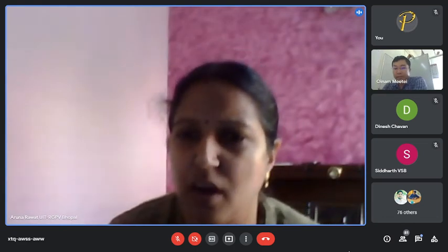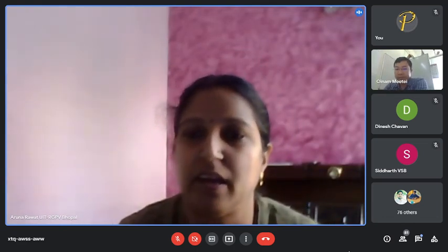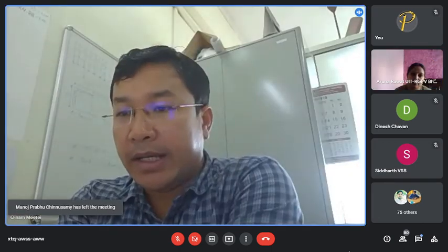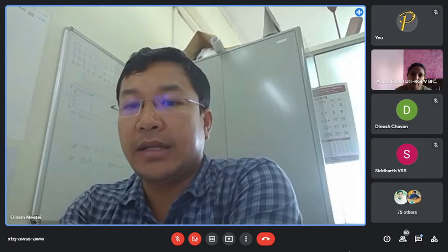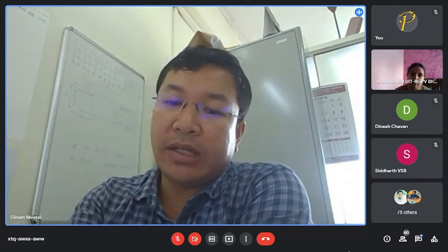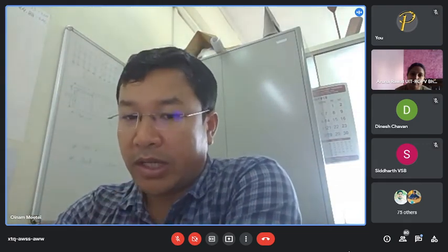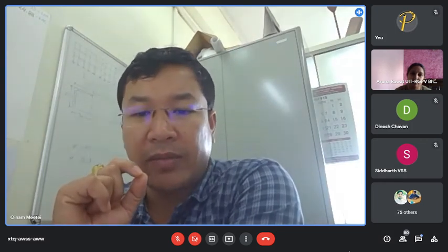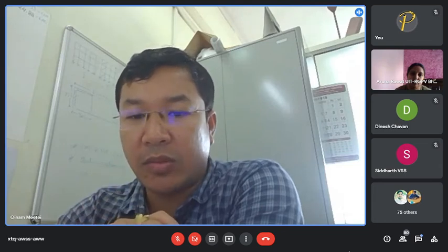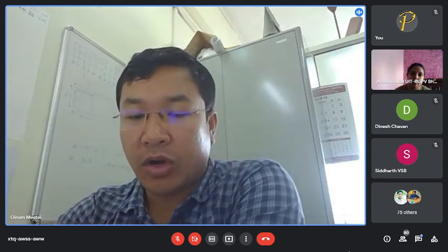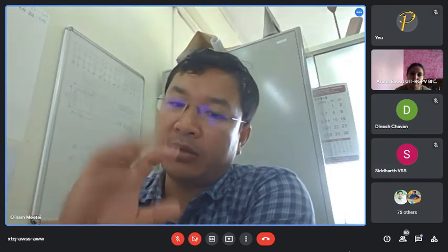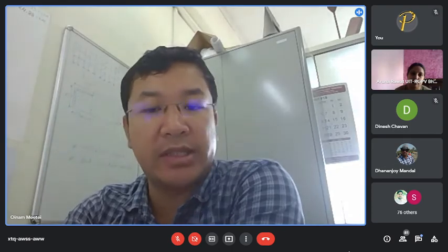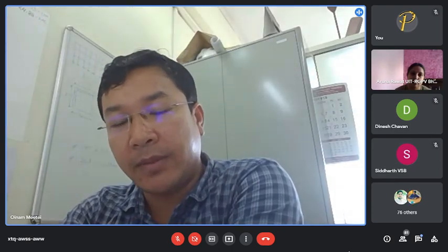There is one more question: how to perform incremental dynamic analysis? See, some people might think incremental dynamic analysis uses different ground motions, 40 or 50 ground motions. It is nothing like that. A single incremental dynamic analysis can be carried out from a single ground motion. For example, if I take the El Centro ground motion, the normal peak acceleration might be 0.36 g, but there is no need to apply 0.36 g.